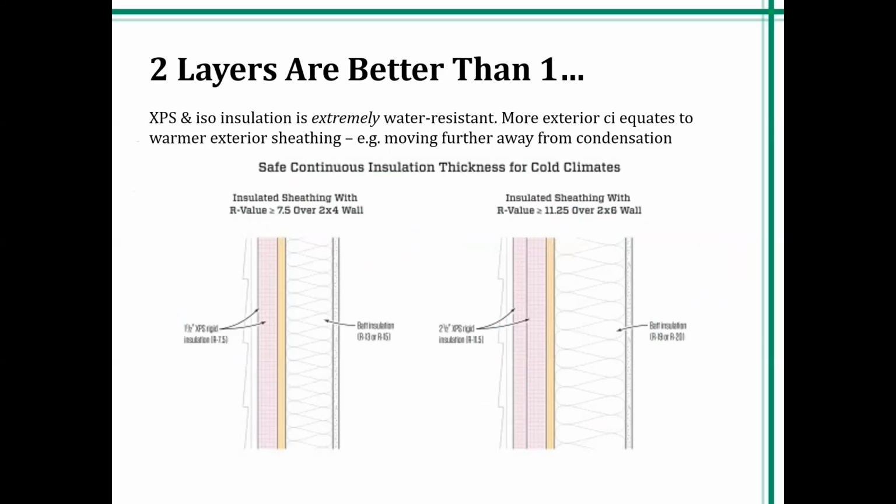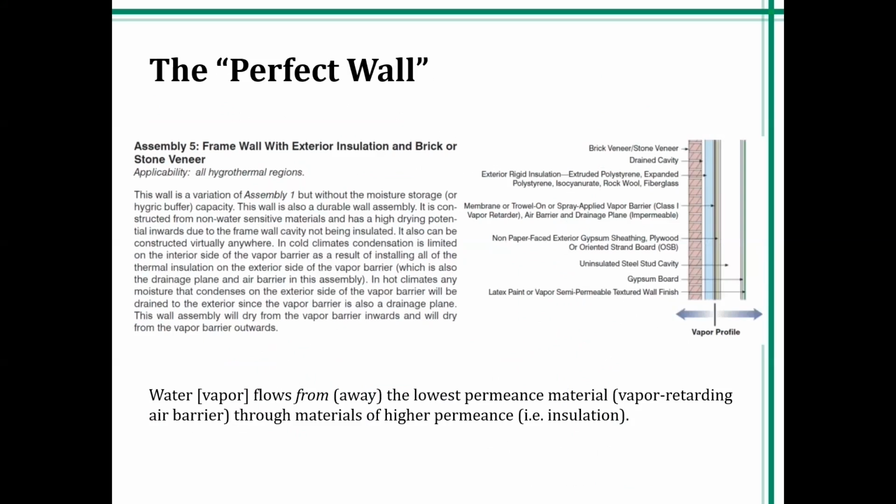I could get into the discussion about dew point collection. I'm not a big fan of it, and I've actually heard the principal of Building Science Corporation mention it as well. But when we place all of the insulation on the exterior side of our wall assembly, the dew point typically will occur at, around, or generally within the primary thermal insulation. And I'm being somewhat vague. If anybody's been involved in hydrothermal analyses, we watch the dew point occur, which is largely going to occur within the insulation. It never occurs in a fixed, static, straight line within the centermost portion of the insulation due to changes in conditions on the exterior.